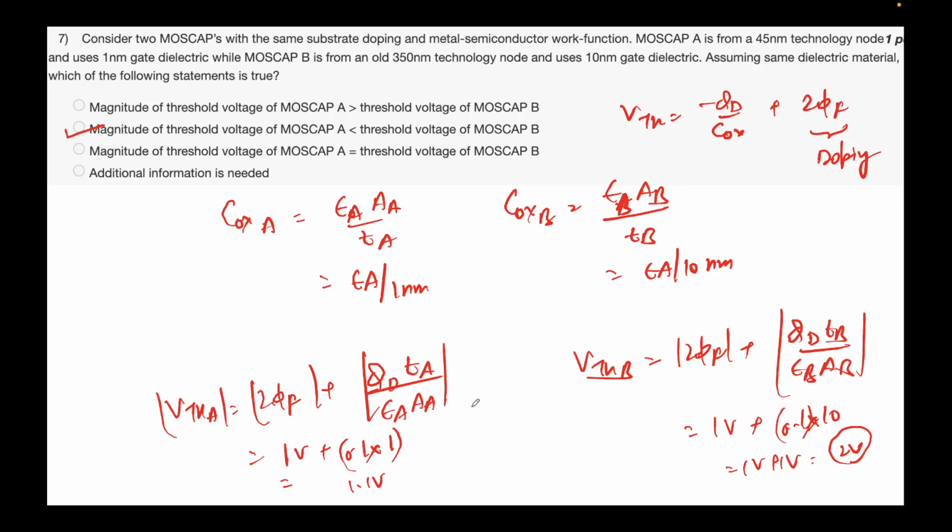It will simply add its flat band. Again, I am assuming phi m equal to phi s, and this is a p-type semiconductor, as you can see, because EF is closer to EV in the bulk. Now let's apply some bias. Let's say this value of Vg, the applied bias, is negative.